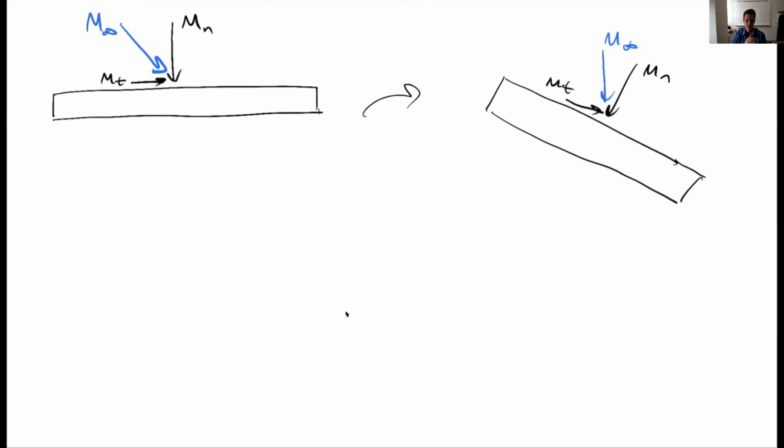So again, the key idea here is that if I was flying a straight wing and Mach 0.6 was causing too much drag, well, I could sweep the wing. Let's just calculate this real quick. Let's say I swept it 30 degrees. So let's take 0.6 divided by cosine of 30. That's about Mach 0.7. So for the same effective Mach number, if I swept 30 degrees, I could get up to Mach 0.7 with no increase in drag, more or less.